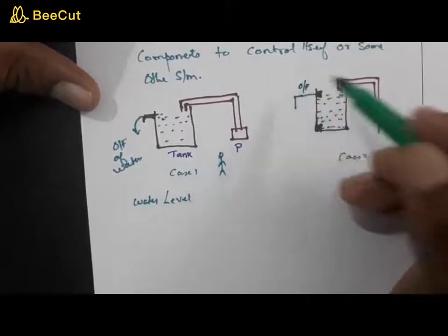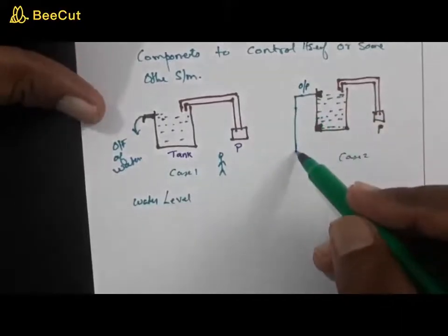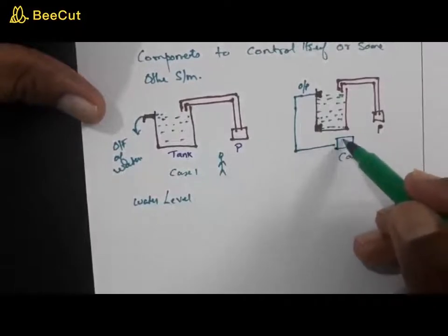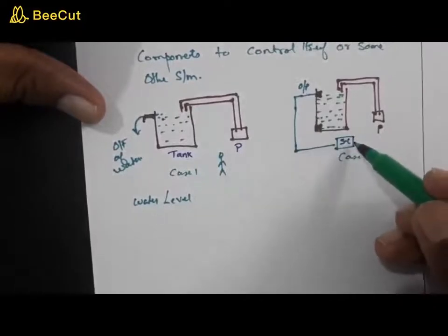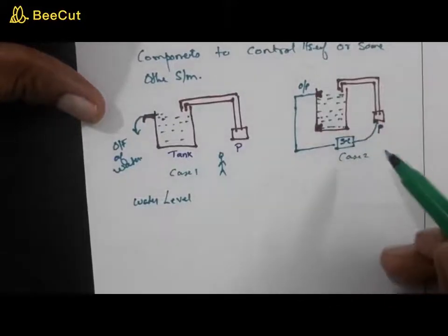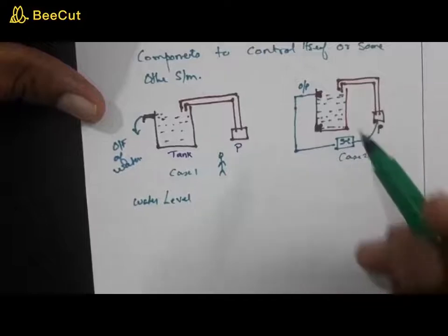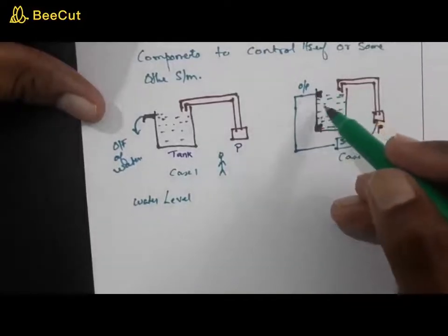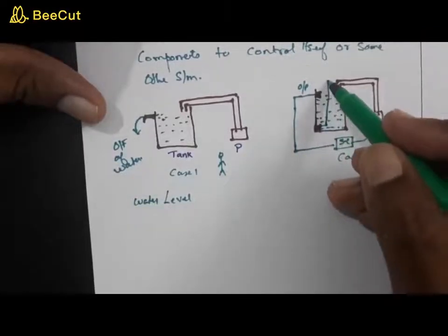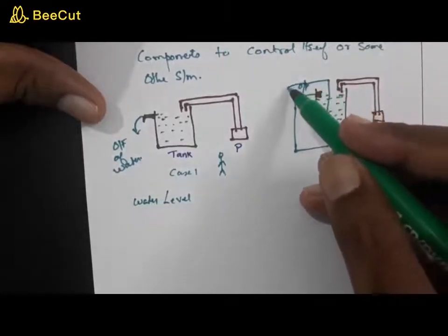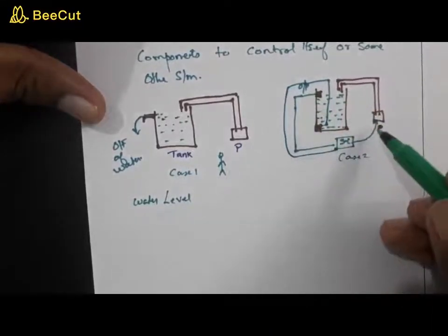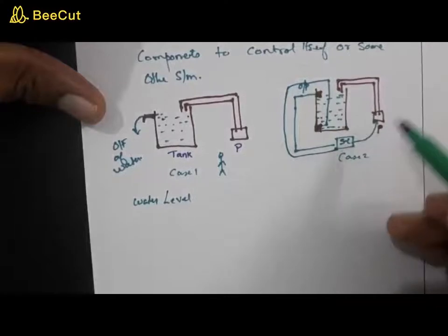You can use this output voltage in a switching circuit which is capable of switching off the pump, imagine that scenario. So you're taking the signals that come from the two sensors, and using this information, you can either switch on or switch off the pump.